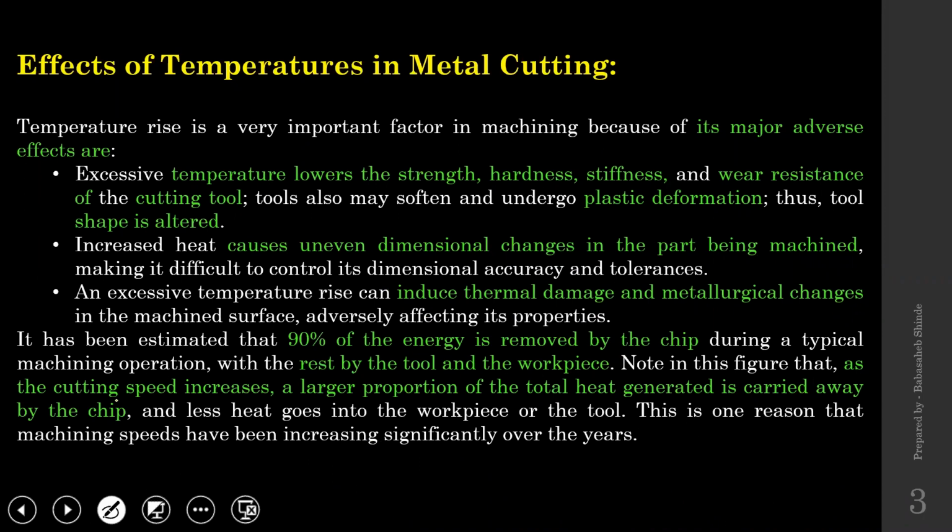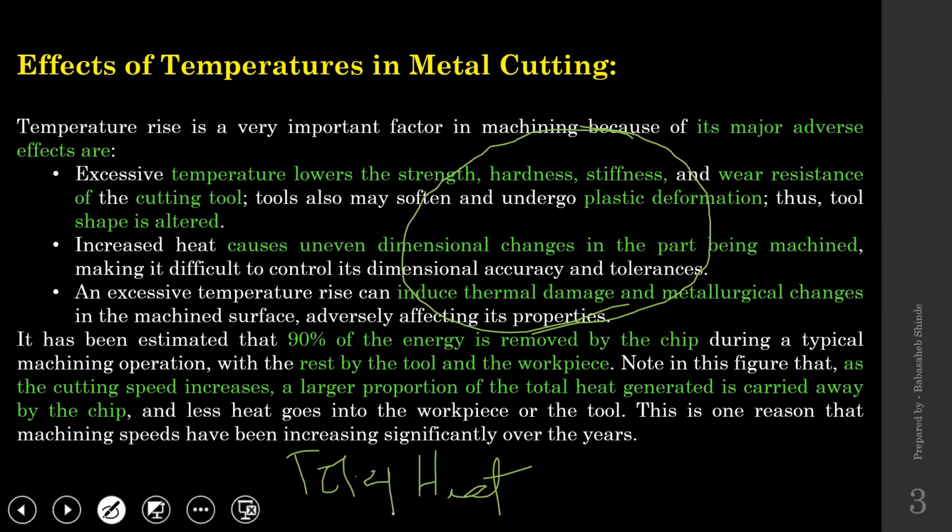Now, as we discussed all these effects that we could observe in metal cutting, let me tell you that suppose there is a total amount of heat generated in metal cutting. Out of that total heat, only 10% of heat is going to cause this. Why? Because 90% of heat will be taken away by the chip.